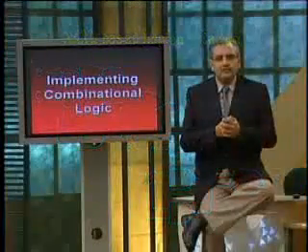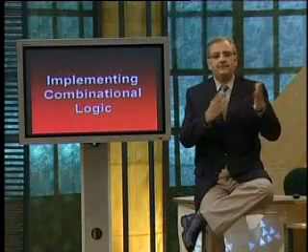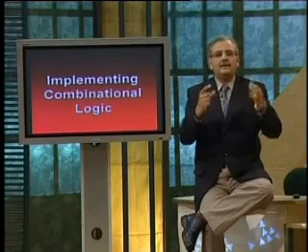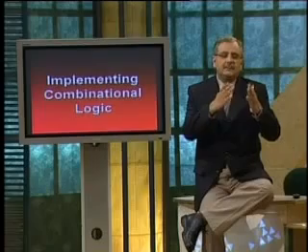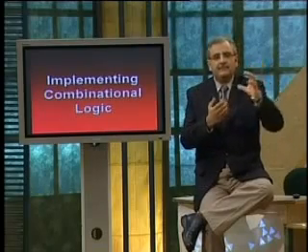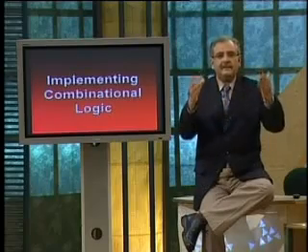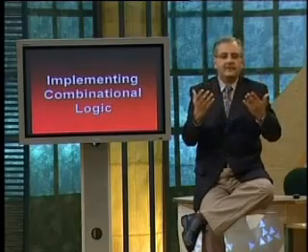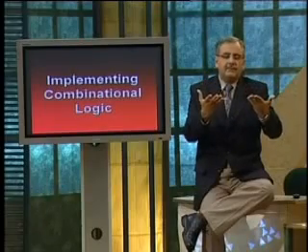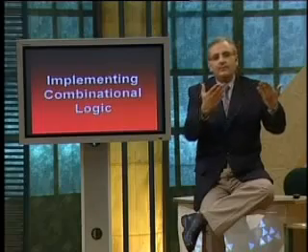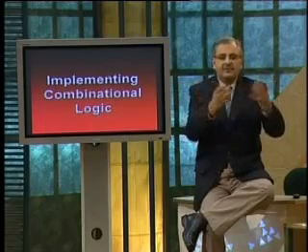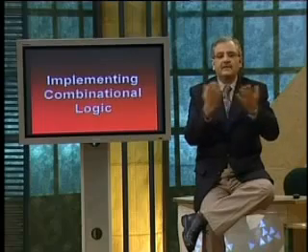We have looked at 3 different implementations of the ones adjacent detector circuit. Basically, we started with the standard sum of product expression. If you look at the function table, you see different min terms. If you write all those min terms, you would have a standard sum of product expression. If you implement each min term directly through an AND gate, you would have the complete circuit. Now this particular circuit requires a large number of gates, so the circuit size of course increases.